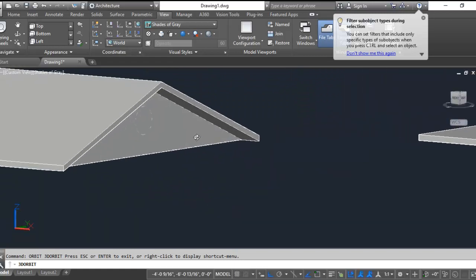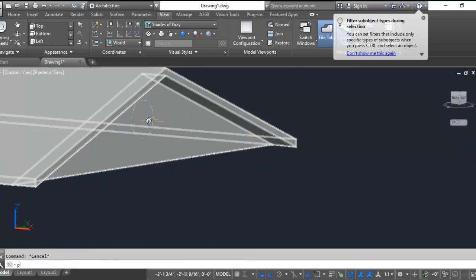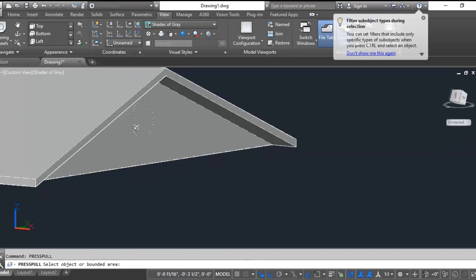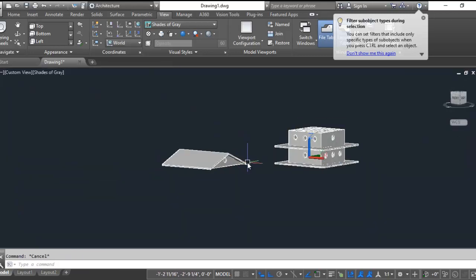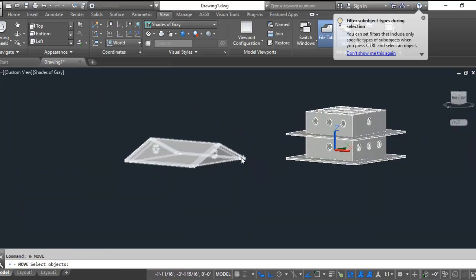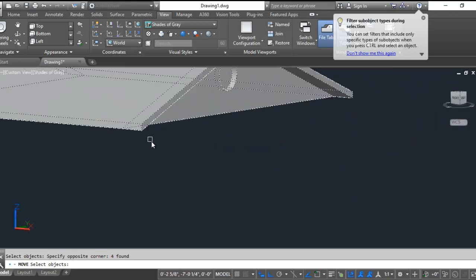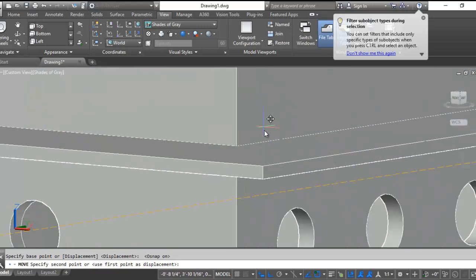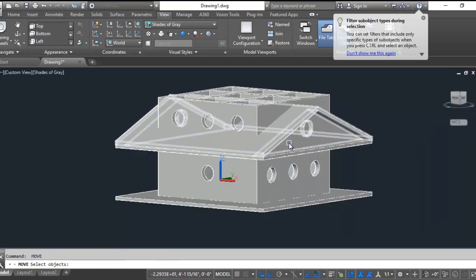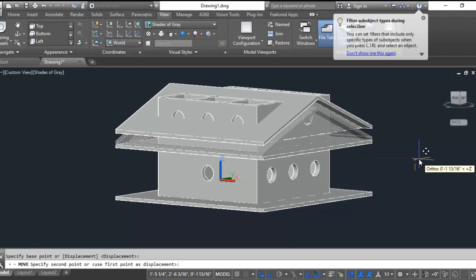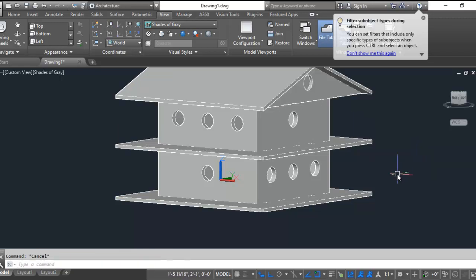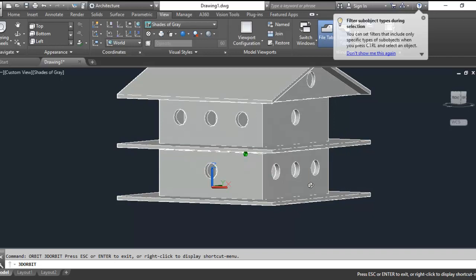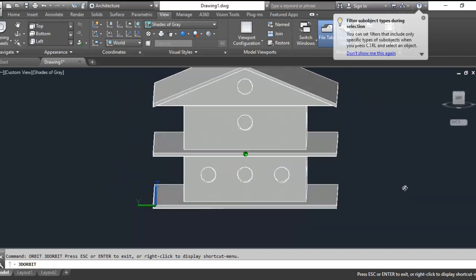Come around to the other side, press pull, go just on the inside of that circle, drag your cursor backward, 0.5, there it is. Now let's place this roof where it belongs. So pick the roof, go from the very corner and drop it on the corner of the second floor. And you guessed it, we need to jack the roof up exactly 7.25 so it sits on top of the 1x4s, and when we orbit around you'll see that it's all connected nicely.